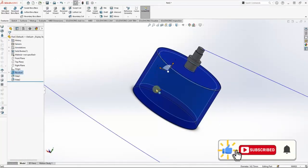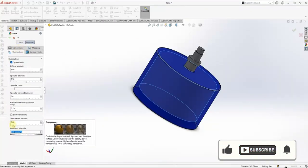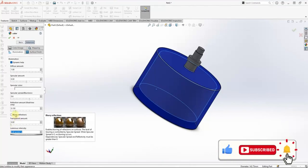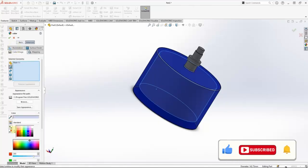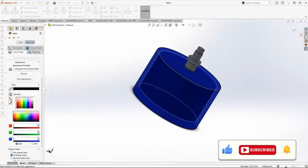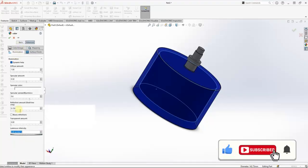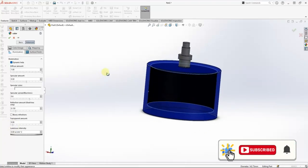And for the inner surface, click on it and come right here to edit appearance. So we're going to be making this a little bit much deeper. The color has to be kind of deep. So transparent amount. Okay. And also come right here to colors. Click on the dark. Let's make it black. And illumination. Ready. Kind of black.